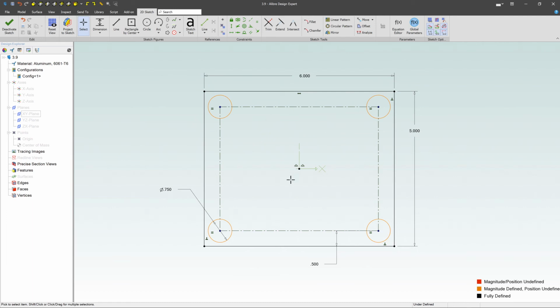But this is one of the best ways to do that, and offset and then switch over to some reference geometry. But you can also use it for a lot of different things. And if you're just doing a layout over a building or a piece, and you just know the specific offsets you're going to be doing, it's a great way to just type those values in, offset those lines, and you can get all that data real quickly based upon some starting sketch. Anyways, that's the basics for offsets. Definitely use them; they'll save you a lot of time.